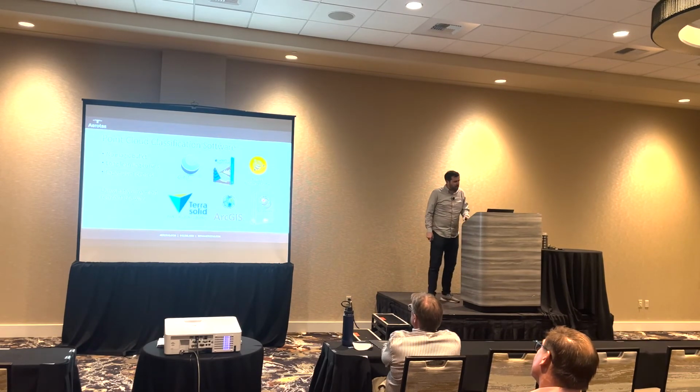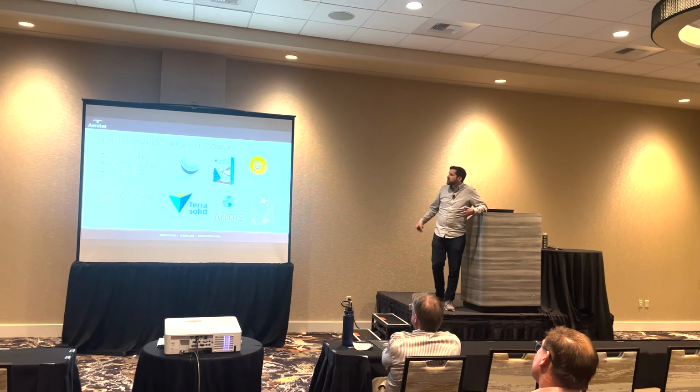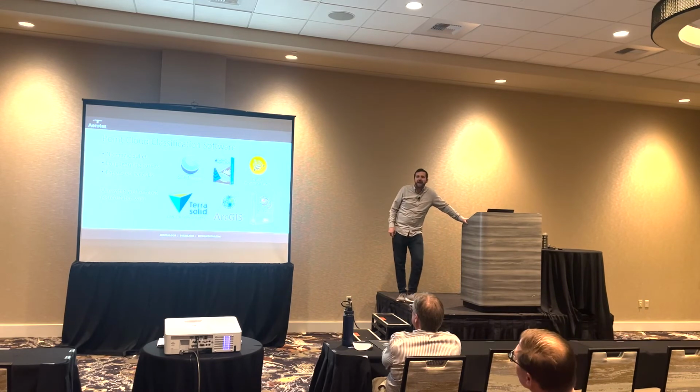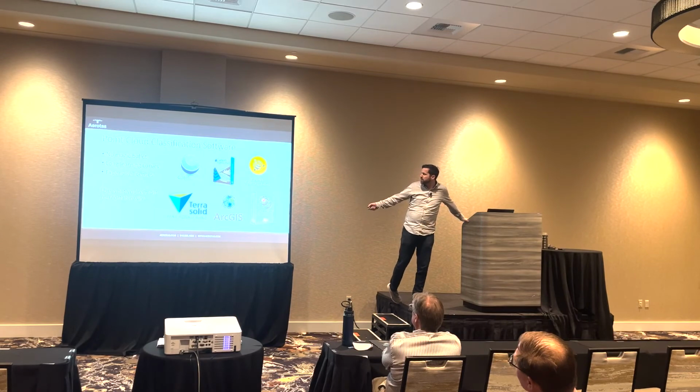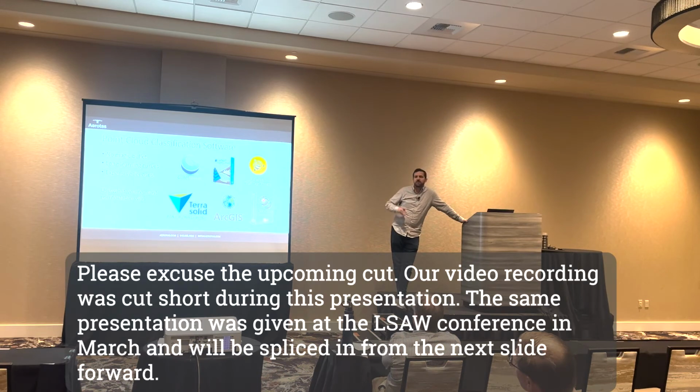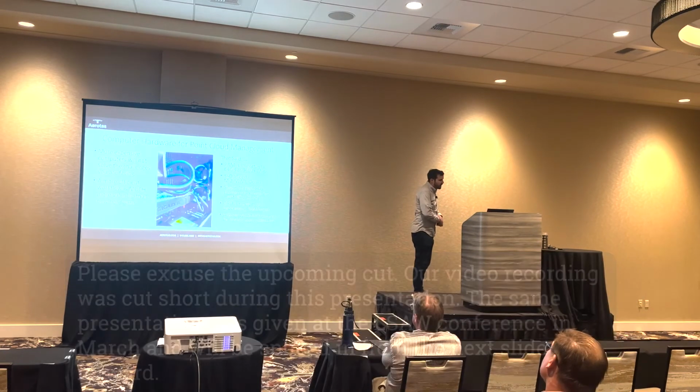Here are the different point cloud classification softwares that we use. Like I said, Global Mapper, Carlson Point Cloud, TDC, TerraSolid, Leica and ArcGIS. We have used most of them, and none's perfect. We don't actually have an active recommendation for all of those. The two on the left are the ones that we use most, but the most important thing is if you're in the ecosystem, if you're familiar with the software, use the one you're familiar with, because the learning curve to actually get up and running with new software is probably one of the more challenging parts.